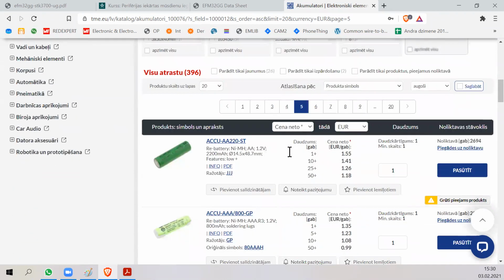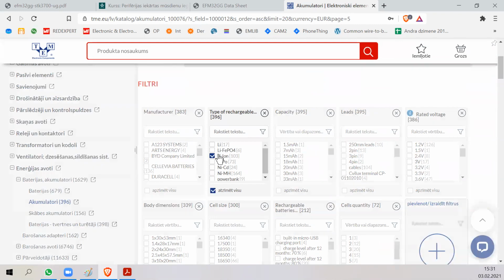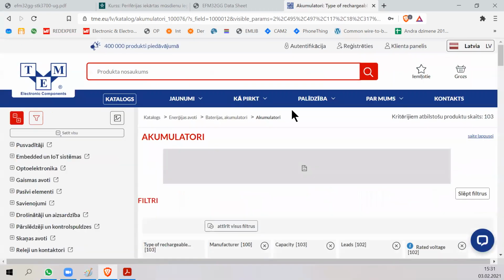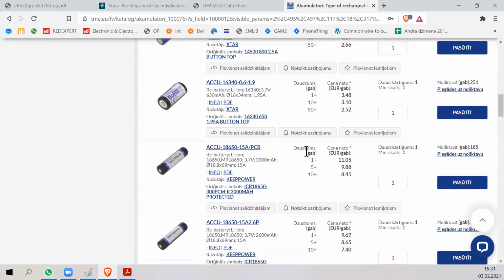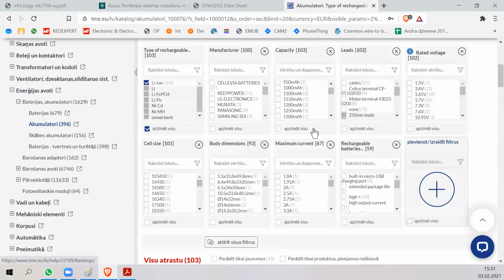We should build that for that, or we should use an external circuit. Yes, you should put a protection circuit on the PCB. But the problem is that in another project, we had problems certifying these batteries because during the tests, they short circuit the battery and the battery may not explode or burst in flames. It's forbidden.